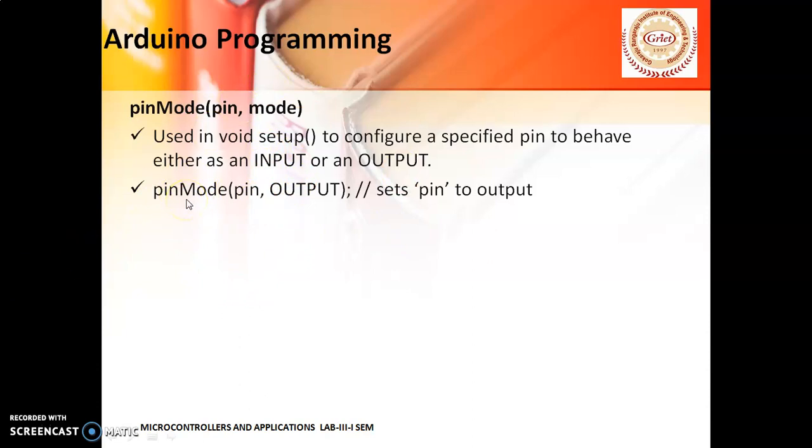So in the Arduino IDE, whatever syntaxes you use, it is case sensitive. So you have to use M as capital here. And in the mode parameter, the mode should be in capital letters. It can be INPUT or OUTPUT. It should be in capital letters.